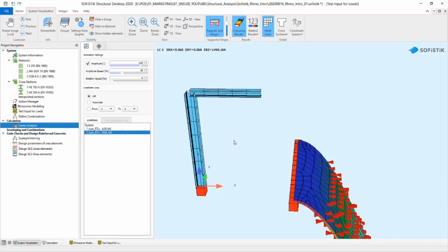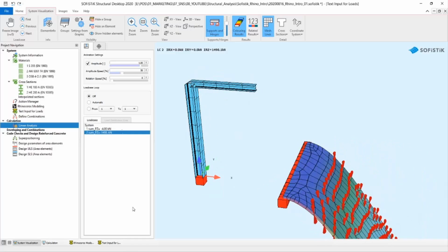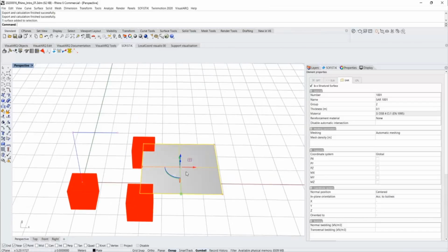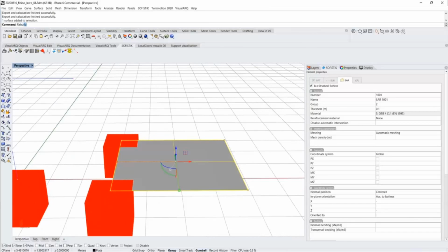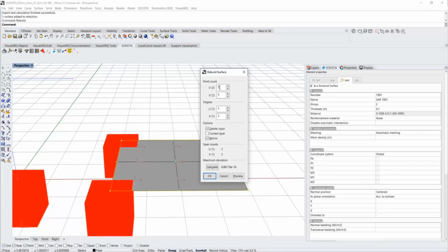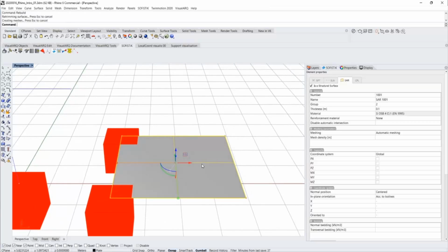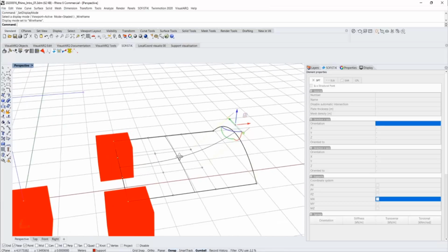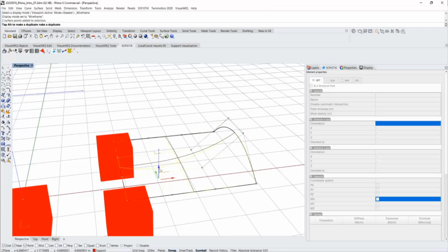And what is interesting now, what if we change the geometry here for the plate? I'm going to rebuild, and I'm going to divide it to 4x4 in the UV direction. So if you look at F10, that's our new UV grid for this surface. And I'm going to manipulate the geometry a bit more, so, you know, we have complex